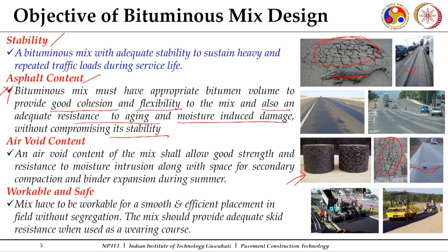So, what you need to see? You need to see the asphalt content which is appropriate for a mix, and that it gets good strength out of it. Air void content: when you prepare these bituminous mixes in the lab and field, there will be some air entrapped. They will not be completely voidless mixes. A general conception is that the more dense a mix is, the stronger it will be. Yes, with the increase in density, the load carrying capacity can increase, but there are certain challenges also which need to be understood.